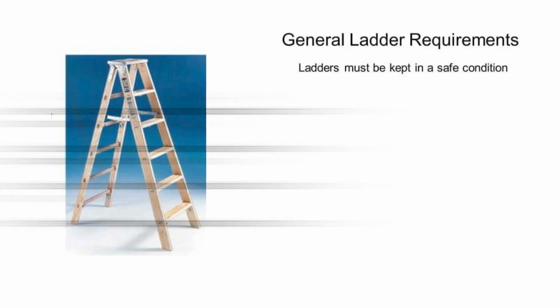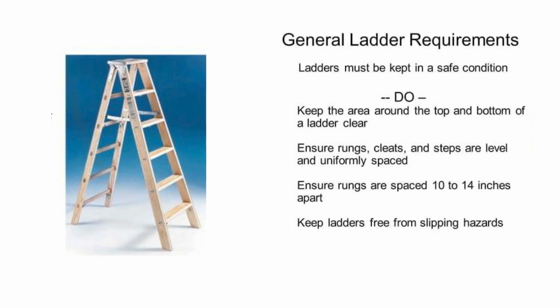Now, we see the do's. Keep the areas around the top and bottom of the ladder clear. Ensure rungs, cleats and steps are level and uniformly spaced. Ensure rungs are spaced 10 to 14 inches apart. Keep the ladder free from any slipping hazards.